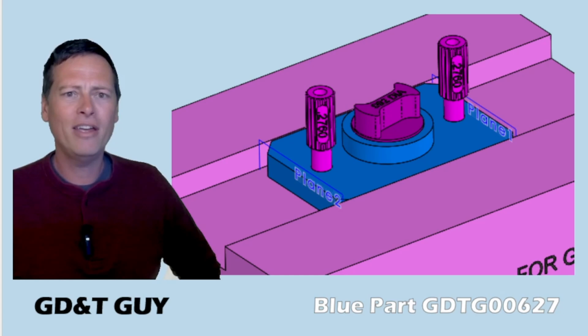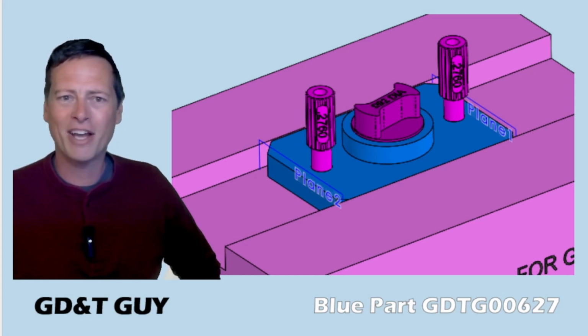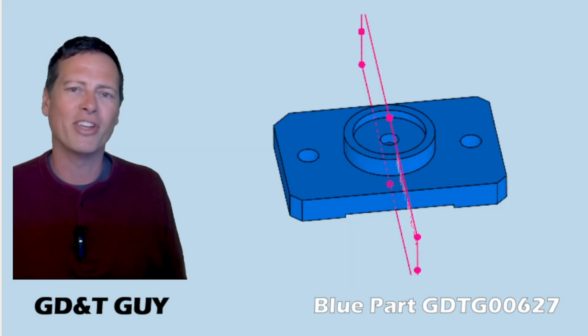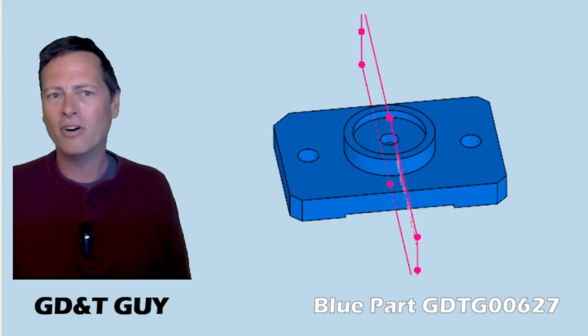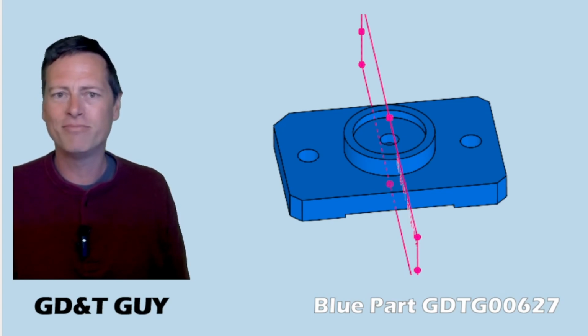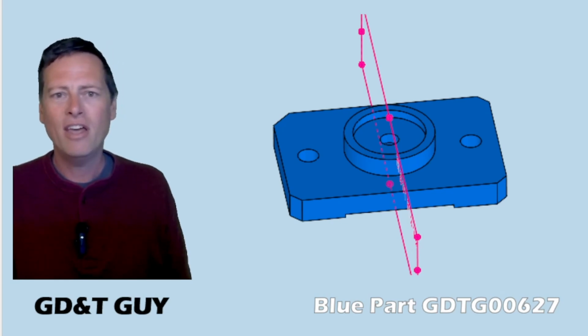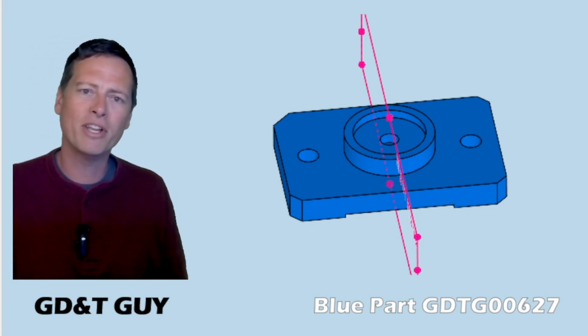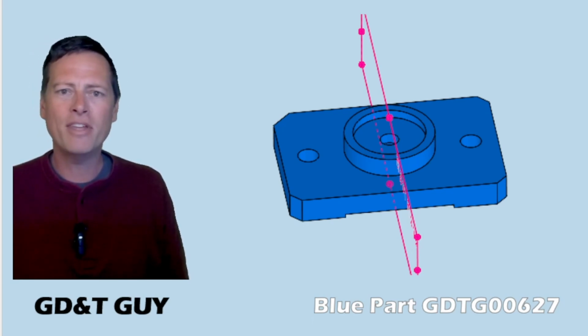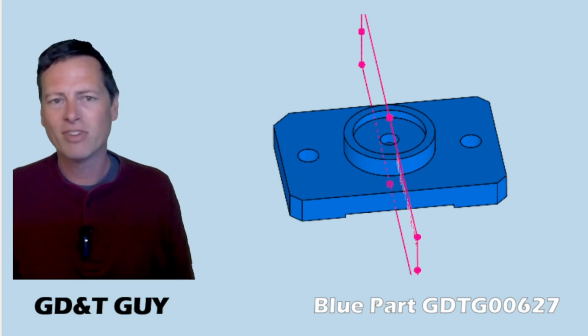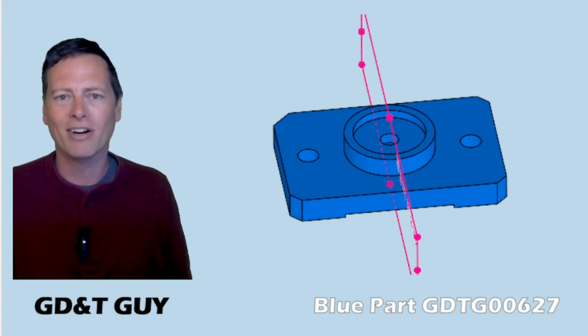If we do it that way, are these boundaries really effectuating a datum? Which is more like a datum simulator here, the center plane of these boundaries or the gauge elements? But that's just one way of looking at it. If you go full open setup CMM inspection, I speculate you could locate datum C off the ends and then locate the 290 holes in the 1-inch diameter feature, and then do a datum shift calculation. All right, that probably works pretty well.